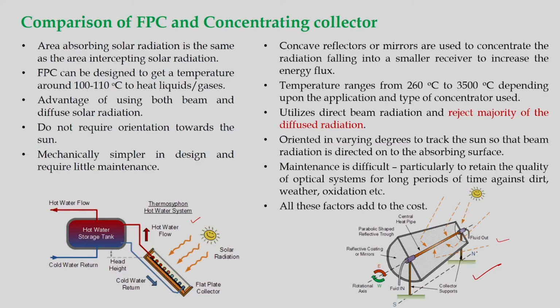Diffuse radiation cannot be employed, or even though diffuse radiation falls on these devices, its contribution is very small. Here no tracking is required, but in concentrating collectors tracking is a must, and because of this it is mechanically unstable and requires maintenance, whereas in flat plate collectors maintenance is very little.